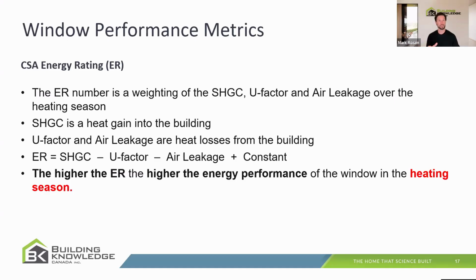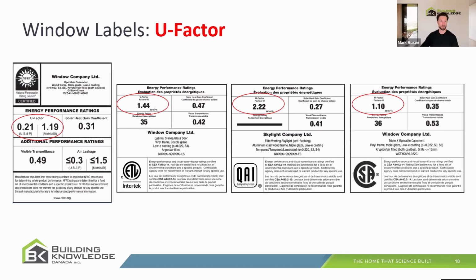There may be situations that we'll see in a few slides where you don't want to capitalize on a lot of the sun's energy coming in at unexpected times and influencing your heating design and your comfort in unexpected ways. And so I will hopefully start to convince you today that U value and solar heat gain coefficient should be your starting points for evaluating your window selection in priority over the energy rating of the window and the number that you see there.